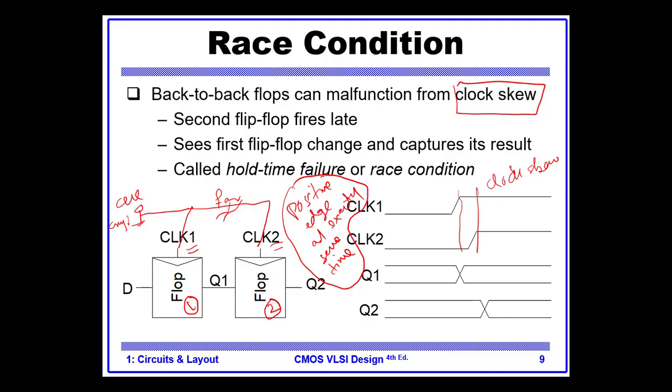And if that may not happen, if there is a delay, then there is something wrong that can happen. And what wrong that can happen is this one. For example, there is a delay in these two flip-flops. This is called clock skew. Due to the clock skew, actually at the output of flip-flop 2, first you should get something like that. You should get first Q1, and then after a certain amount of time the state changes and you get Q2.